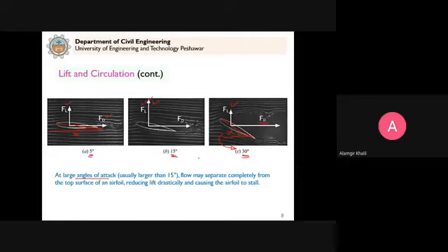They conducted a large number of experiments in the 1930s and around that time. Because we were then designing aeroplanes, they conducted these experiments to come up with the optimum values for this angle of attack, so that the drag force can be kept minimum and the lift force can be increased, as we want to fly the aeroplane high in the air. Clear? So you can see that if the angle of attack is greater than 15 degree, which is shown here,